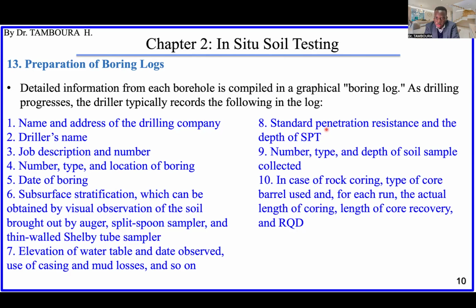So in that case, the type of core barrel used, and for each run, the actual length of coring, the length of core recovery, and the RQD need to be noted, need to be written in the report, the boring log.